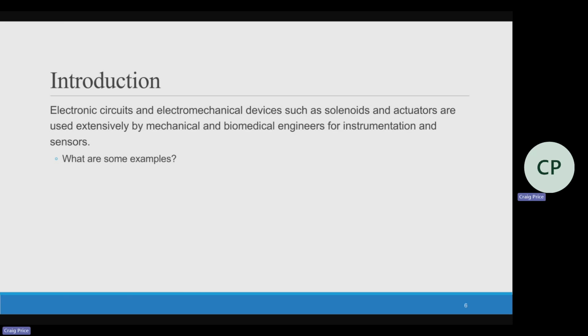All right. Do you have doors in your car that you have to crank closed or locked, or do you use a key, or do you sometimes just hit a button? Hit a button. Okay. So those are solenoids right there. You hit the button, it tells the car to power the solenoid. The solenoid moves position, then it locks the door. So that's a pretty quick example. But obviously, robots around here have different actuators. It's used in HVAC as well. Anything to open or shut is typically a solenoid.